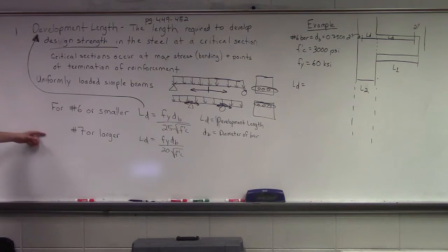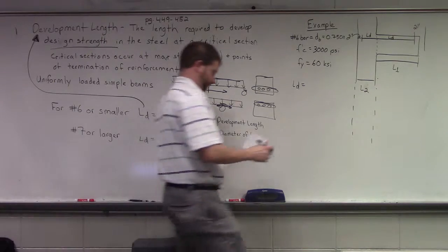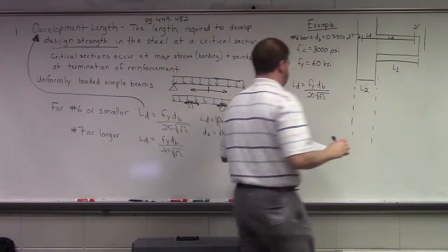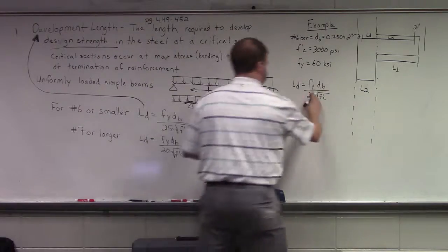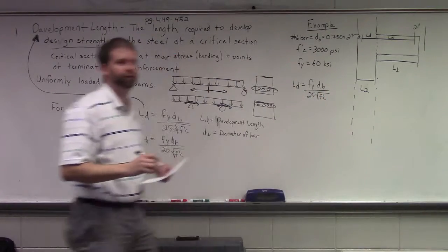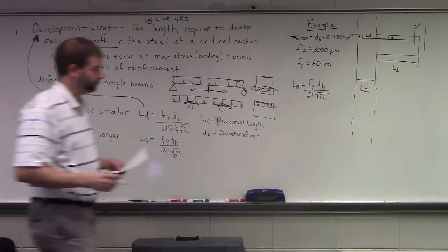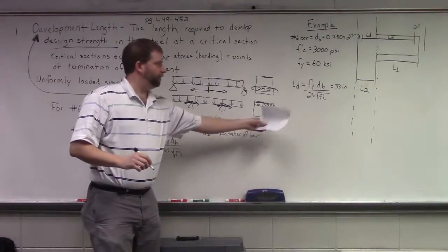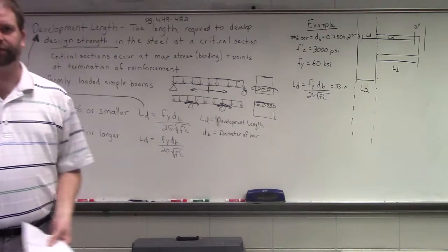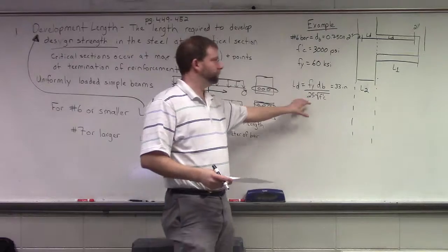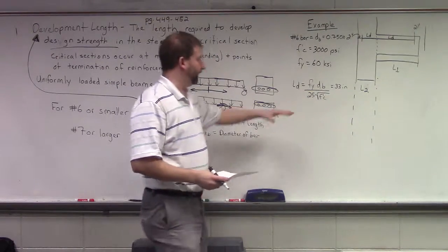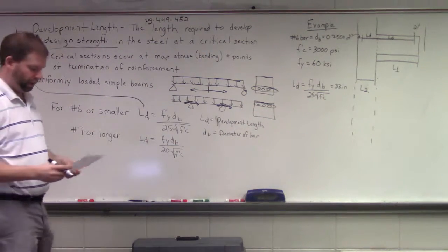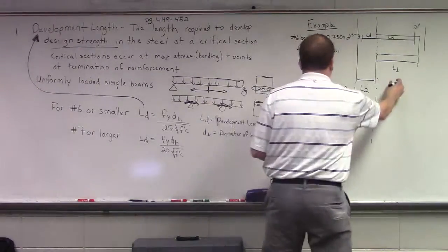Which equation are we going to use? First one. We're going to use the top one. Okay? So I'll use the top one. Put in 25. Okay? Crank through on this guy, it actually comes out to be 32.857 or something, but 33 inches essentially. Okay? That's what we need for our development length. That's what our LD calculates out to be. You need a complete answer. Yep.